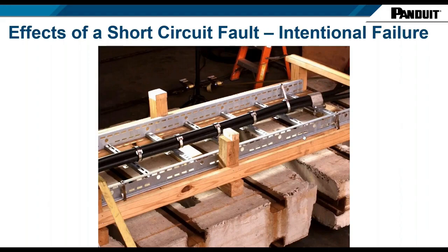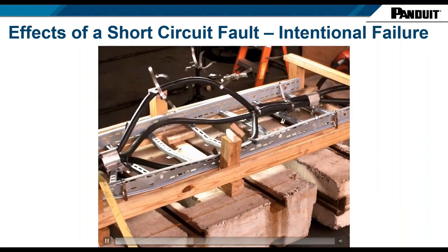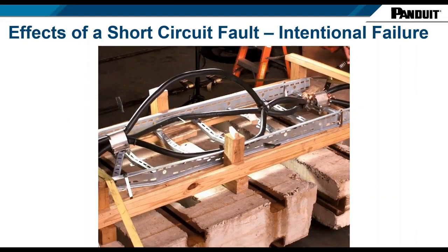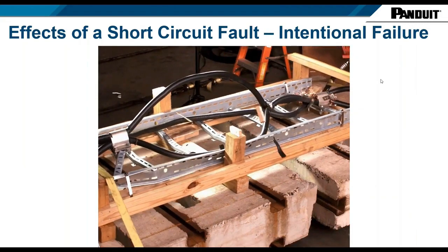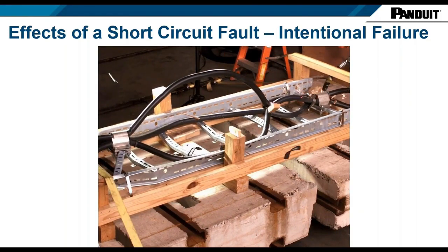This is a product produced by Panduit, but we aimed far too high on one of our initial tests. So we run the high-speed video at 10,000 frames per second, but as we saw in the graph, this all happens within milliseconds. Now, all of this movement is purely down to the proximity of those conductors. They are touching in trefoil. The fault force turning basically into electromagnetic force.